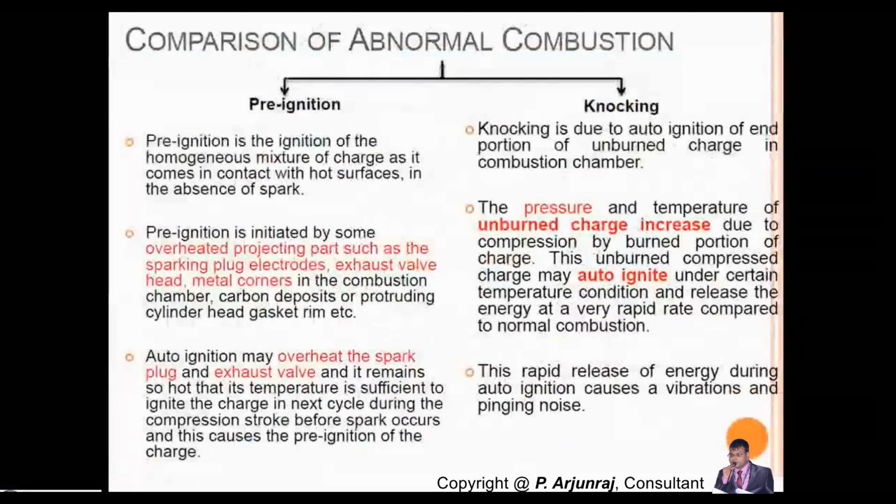Now we'll see what knocking is. Knocking is due to auto ignition. There is a difference between pre-ignition, auto ignition, and knocking. In knocking, you get auto ignition of the end portion of the unburned charge in the combustion chamber. You have the burned portion and the unburned gases. Knocking develops because of the auto ignition of the end portion of the unburned charge. It is not happening because of the burning.